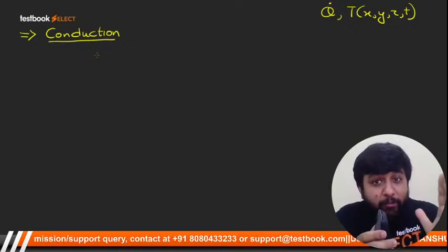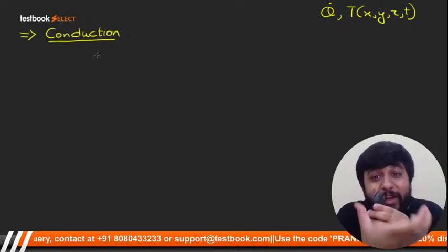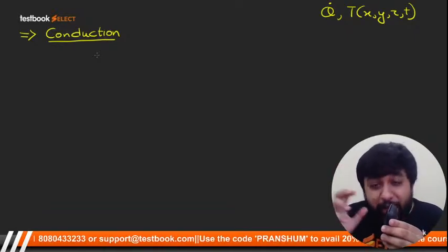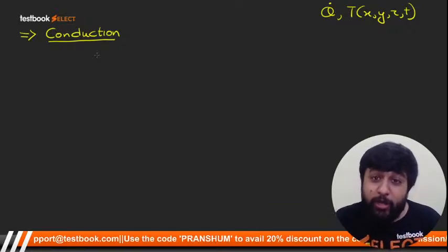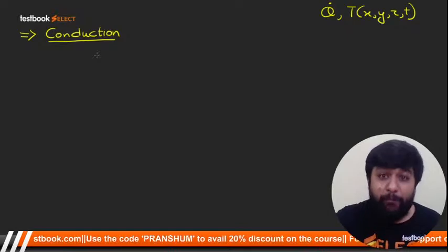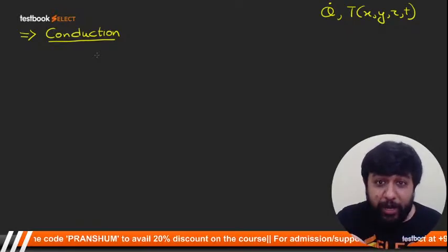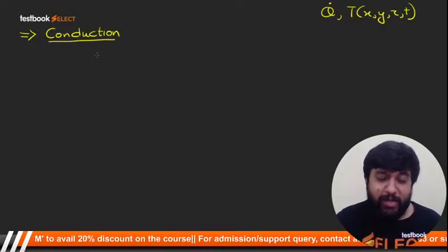But when here the temperature is high and here the temperature is low, then with the temperature difference, the same lattice vibration will help you carry heat. So heat transfer will come into the picture. So the activities always happen, but until and unless there is a temperature difference, we will not get heat transfer. We saw this in the last class.